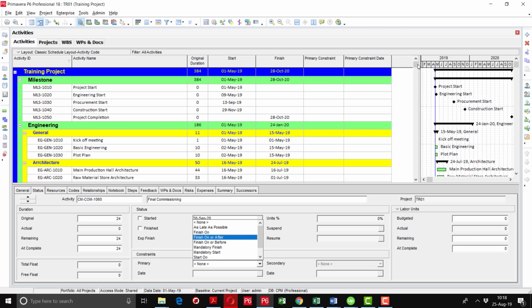So you have to put a milestone in the schedule. If he fails to deliver the slab on the required time, obviously your activities will slip further. If he is delayed at his end, your activities will ultimately be delayed, but your delay is dependent upon other contractors. In this way you can get the EOT from the client. So that is the advantage of the constraint.